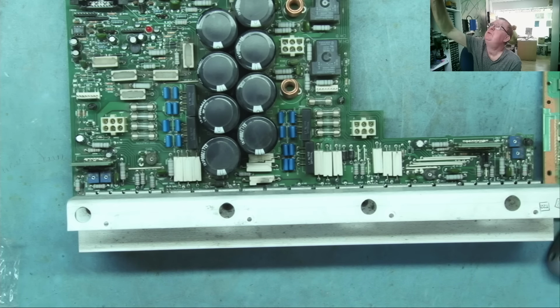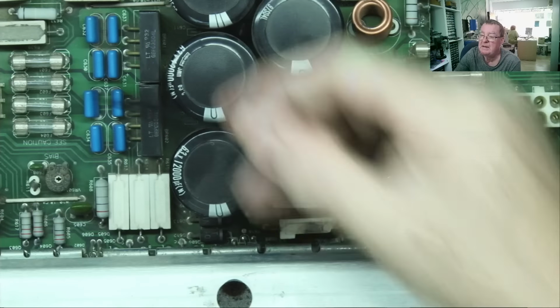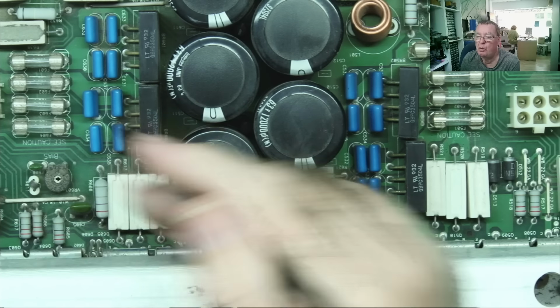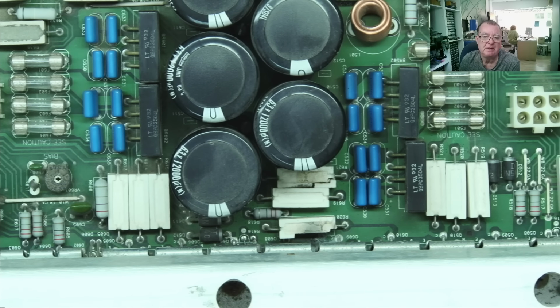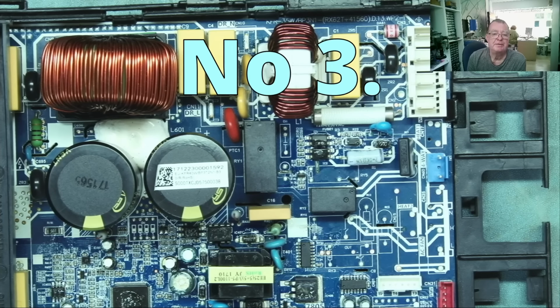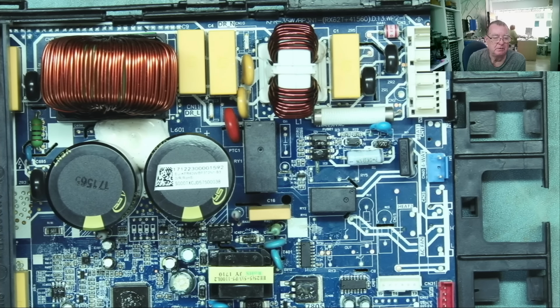Last thing about fuses, often when a fuse fails, it's visible. These look okay. Look okay isn't the same as is okay. So just bear that in mind. Always test them with a multimeter. Make sure they read short, which is short if it's a good fuse. Number 3, heavy components. Physically heavy components.